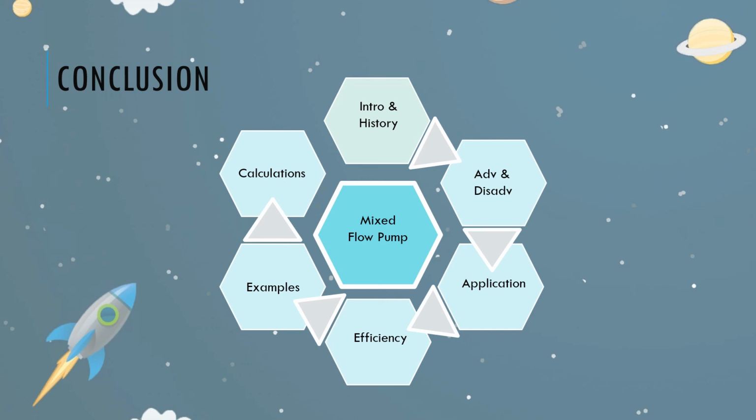However, we also acknowledge the fact that a mixed flow pump is a type of pump that mixes the features of radial and axial flow pumps. It has many applications ranging from flood and stormwater control to filling and emptying of reservoirs, and we've also seen that the major advantage of mixed flow pumps over the rest of the pumps is that they combine higher mass flow of axial configurations with higher pressure achievable by centrifugal machines.